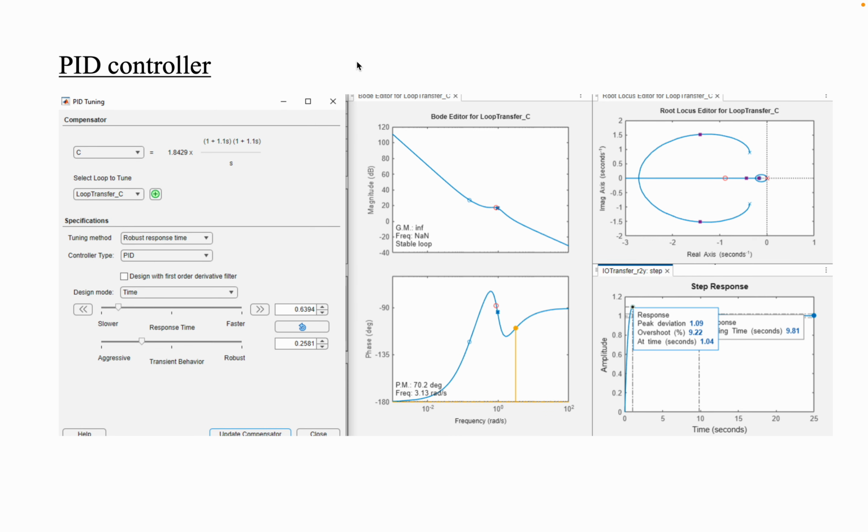For the PID controller, it was the best with fast rise time and no steady state error. In root locus, it shows the best pole position for stability, and in the Bode diagram, it gave the highest margin, making the aircraft pitch control system very stable. Overall, PID control again gives the best control.